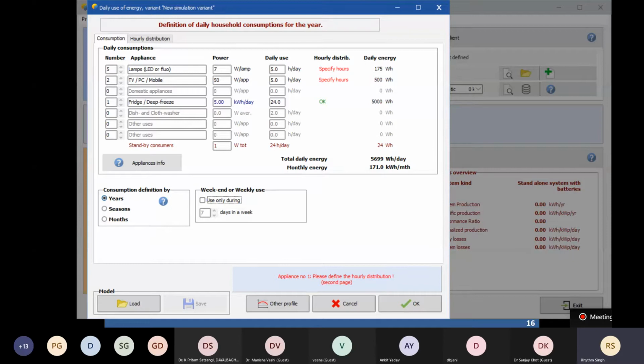And the energy consumption can be any time of the day, across the 24 hours. So whether the energy consumption is during the sunshine hours or the non-sunshine hours, the entire calculation will change. The sizing of the PV system and the sizing of the battery system, all things will need to be accordingly adjusted.